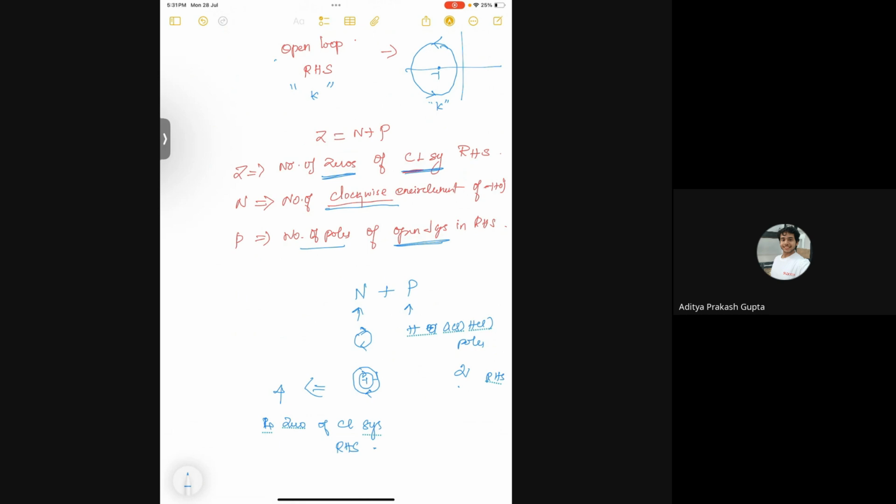So this represents that the system is a non-minimum phase system. It can introduce a delay into the system. The closed loop zeros are in the right half of the S plane. The number of closed loop zeros here is 4. So you can just shift this formula, but you have to be very careful while you are shifting it.